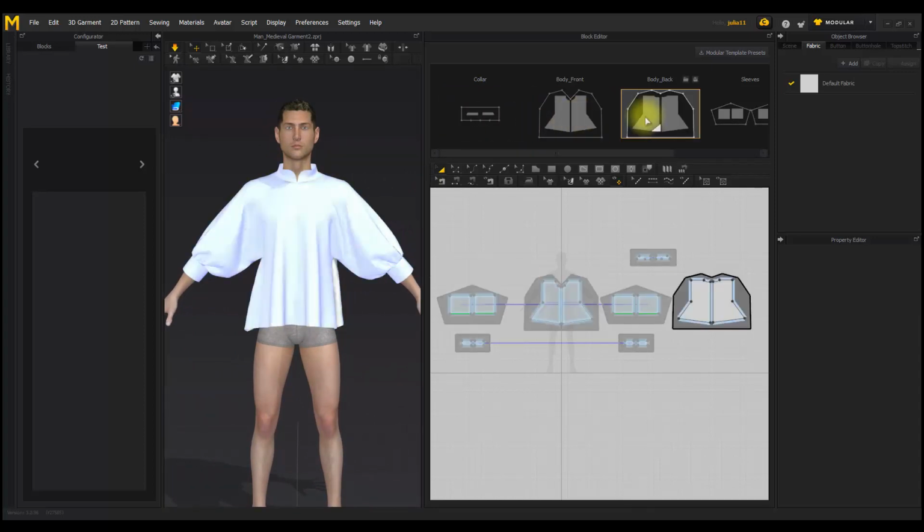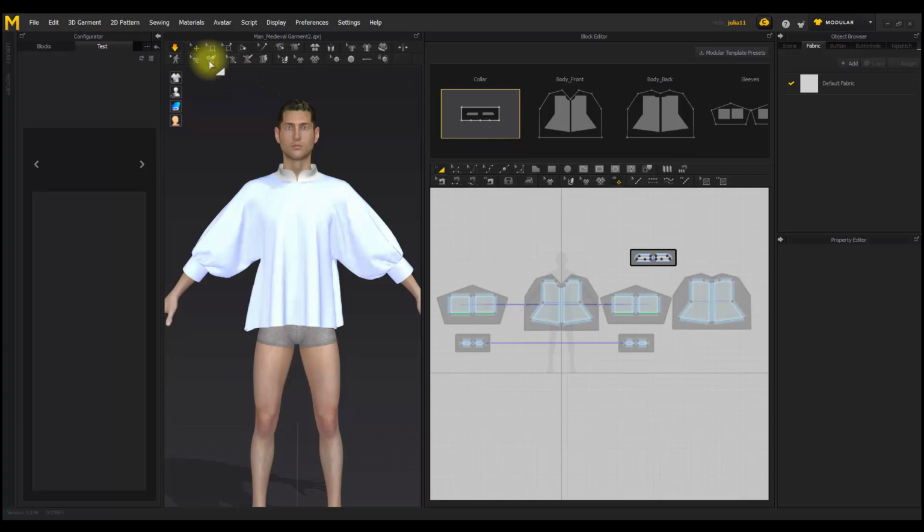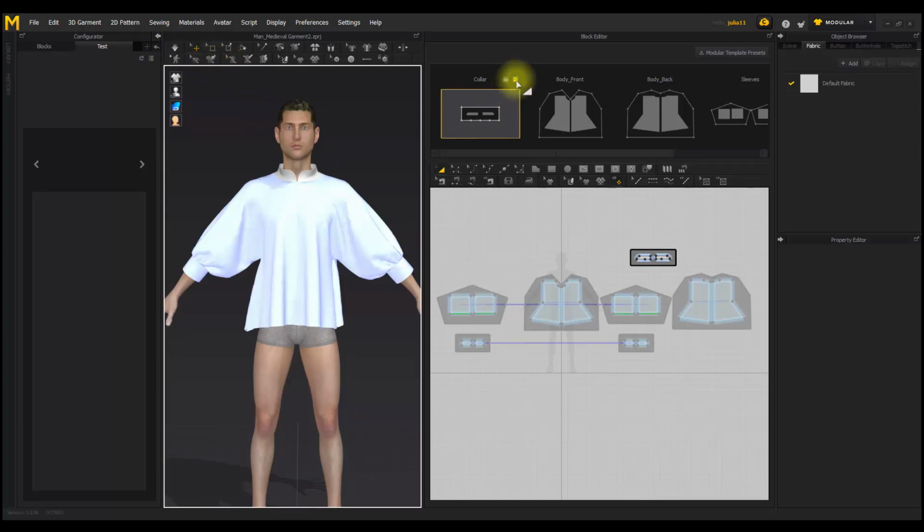In the 3D window, all the patterns except the pattern in the selected block box are frozen. This is because the outlines of the patterns connected to each other must match when saving blocks. To deselect a block box, click the selected block box one more time. Now let's save the block boxes one by one.